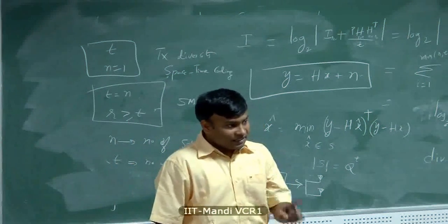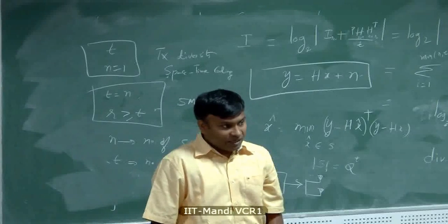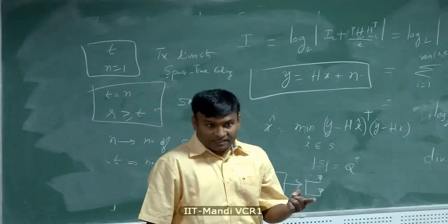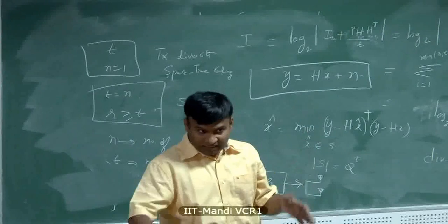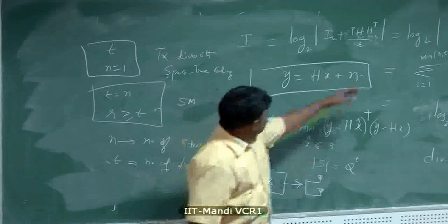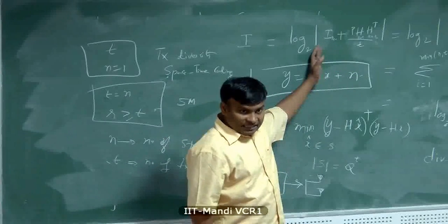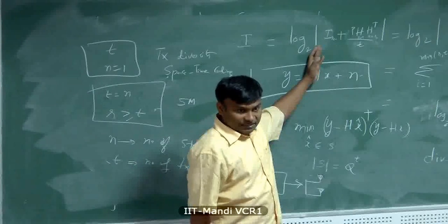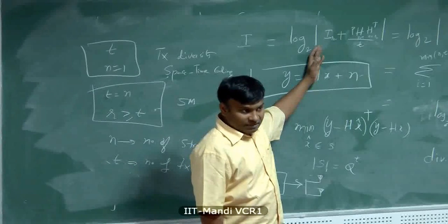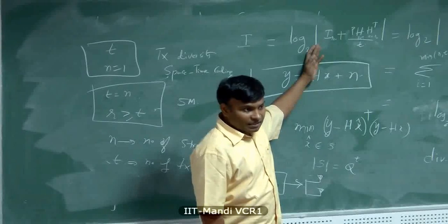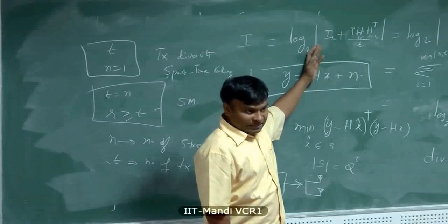Okay, so let me just reiterate. For the MMSE receiver, you have to calculate the capacity, that is average capacity versus SNR, and compare that with the capacity of the channel without CSIT and with CSIT. CSIT means channel state information at the transmitter, that is the H matrix, with and without feedback. The theoretical capacity with and without feedback, and the capacity achieved with spatial multiplexing.